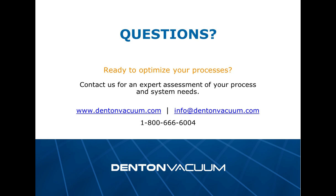Here's one on OMS. Are OMS systems ellipsometry-based, reflectometry-based, or some other technique? It depends on the setup. Usually reflectometry, so you would have a light source directed towards either your substrate or the witness crystal, and you would get the reflected light back as feedback. I could envision in some cases, in the case of transparent substrates and transparent films, it's possible to have transmission, but most likely it is a reflection-based measurement.